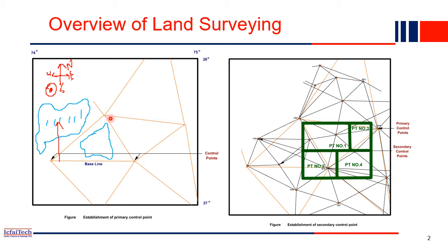So these big triangles now have been divided into small triangles. You can see the entire big triangle has been divided into small triangles. Our main objective is to get as many latitude and longitude coordinate points of the entire area as possible. This process will be further repeated, and we'll make small surveying triangles. Once we have made so many triangles inside the big one, we go inside each triangle, and again we subdivide each plot or each triangle into further small triangles.